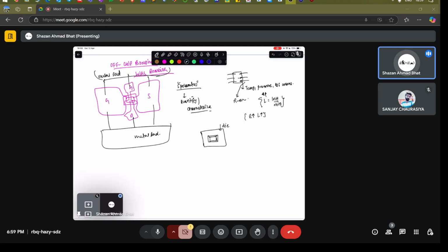Exactly, the hole thickness is exactly equal to that of the chip thickness. Then you put the chip inside the hole so that it exactly fits into this hole, and there should be no protruding part out from this chip. The upper surface should be flat so that when you bring the wire bonding metal wires, they should directly go here instead of going like this.